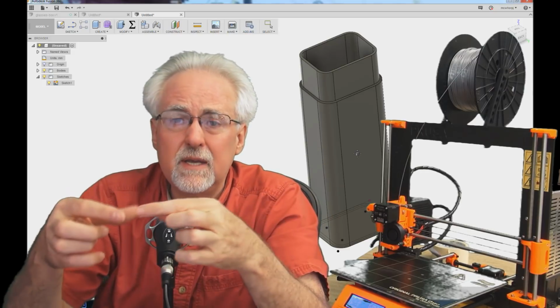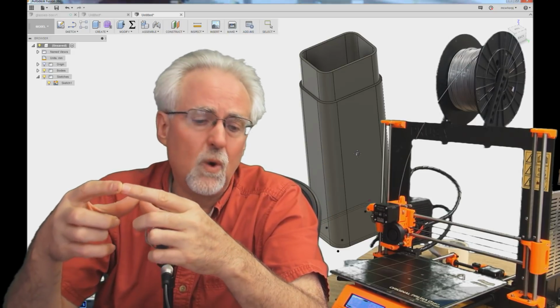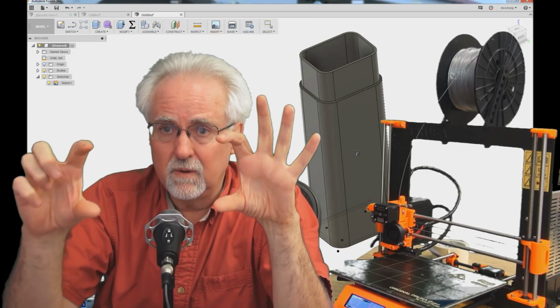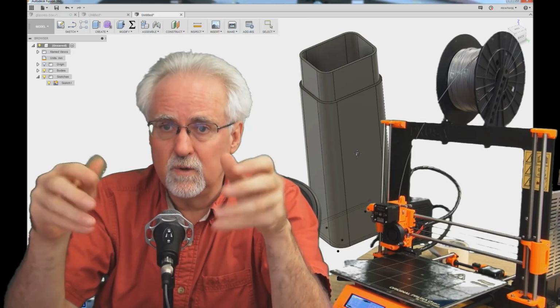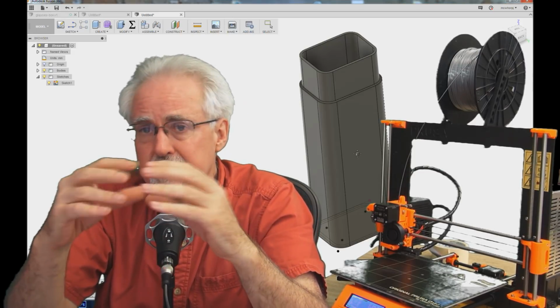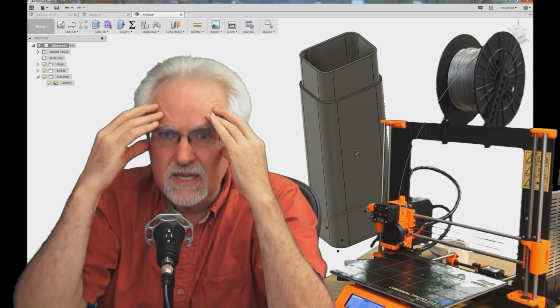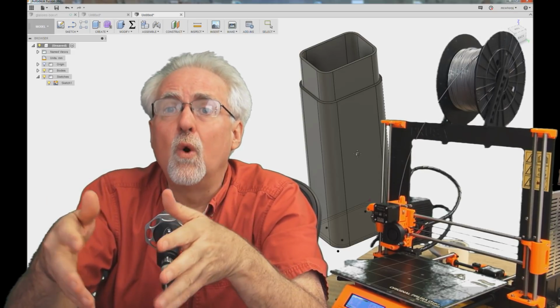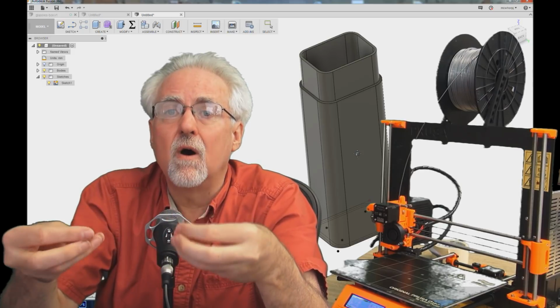Like, imagine if you're making a Raspberry Pi case, what is always going to be fixed? The dimensions between the holes on the Raspberry Pi, those mounting holes, those you would want to put in as fixed parameters, and then what might change is this or this or this, but you would be thinking of that Raspberry Pi box based on how this needs to always work.